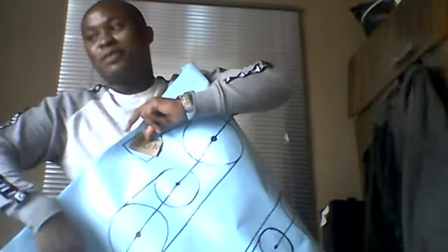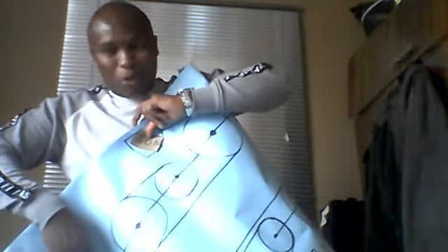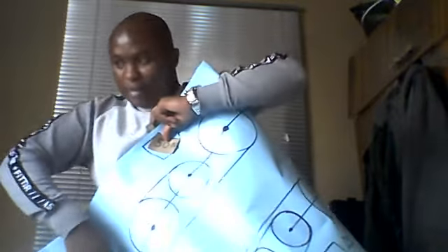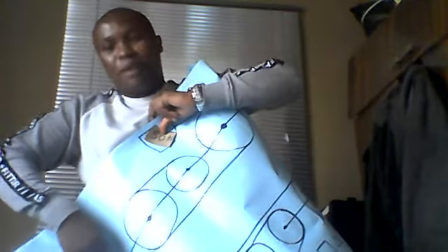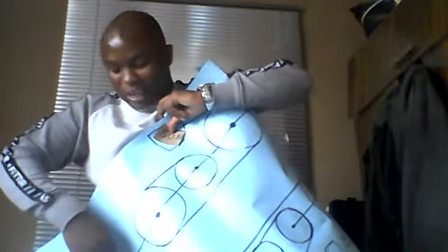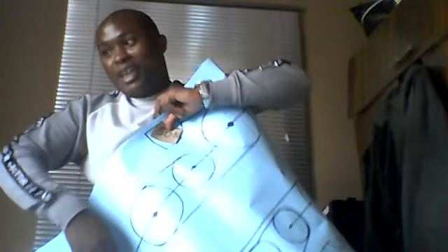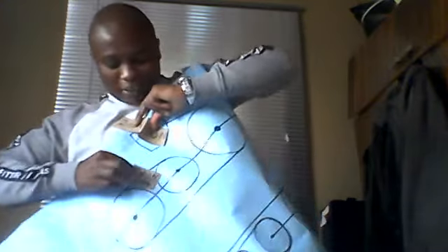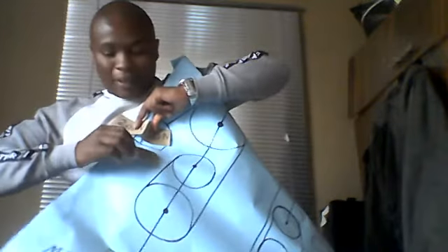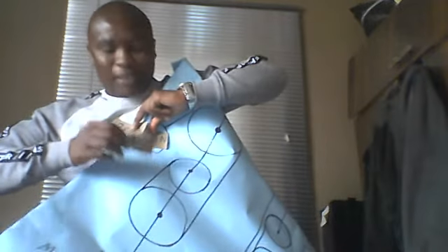So we should calculate the mechanical advantage that is going to be needed so as to pull our load. We are going to say 200 divided by 50. Why are we dividing 200? It's because 200 is our load, so the load is divided by the effort that is needed to lift the load. A typical example will be: 200 divided by 50 is equal to 4. So why am I reiterating this?